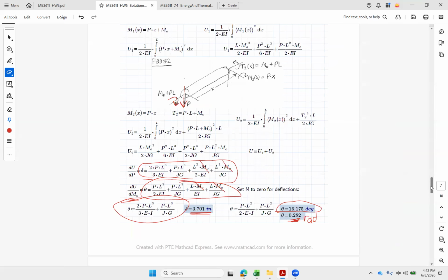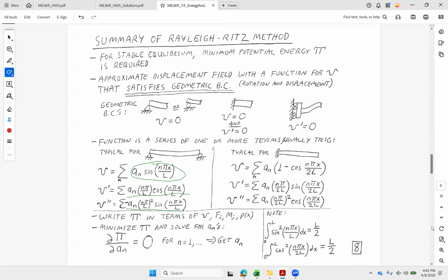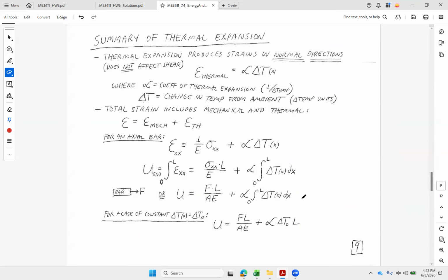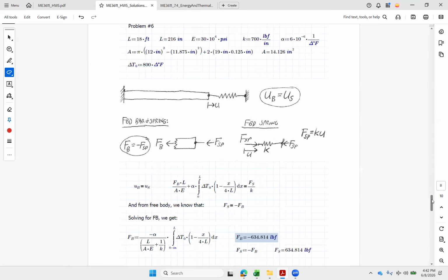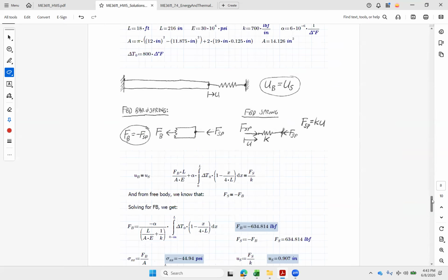And then I have my usual thermal Hooke's law right here for my bar. We can grab that one right there with that load pointing out. And that's everything that I need to set up this problem. Works just the same as any other 2-bar with bars side by side or end to end. F bar equals minus F spring. The way I have them drawn, if I'm pushing in on the spring is positive, the spring pushes back on the bar, and there's F bar. So F bar equals minus F spring, just like we did for any other one.